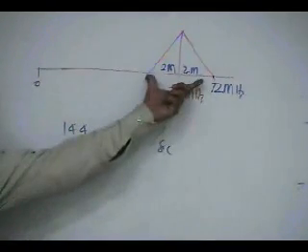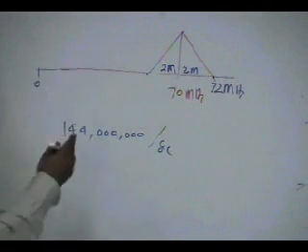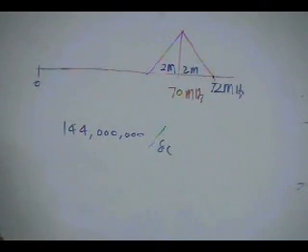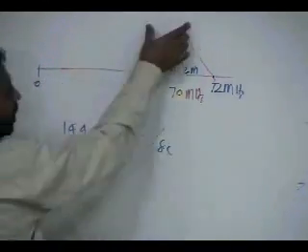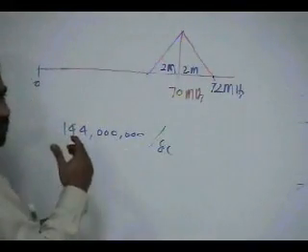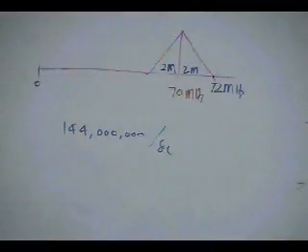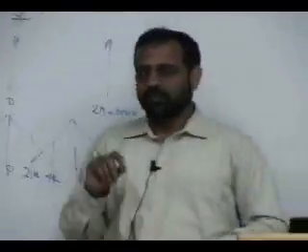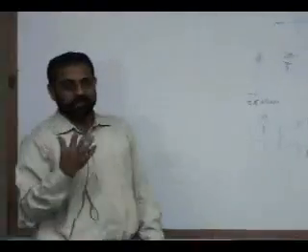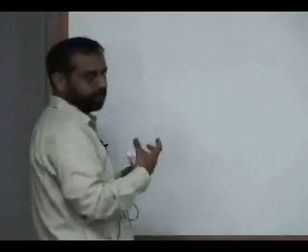But I know actually the bandwidth is only 4 megahertz. If I, by force, alias this, what will happen? If I alias it, I know this will map to lower frequencies. I am only interested in this band. I need to bring this band down. If I don't really sample at the desired rate, I by force alias it to use a low complexity A to D converter, and also to move it down the spectrum, because I have to move this down the spectrum.